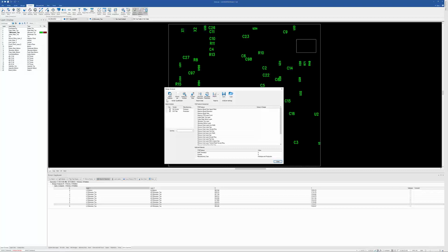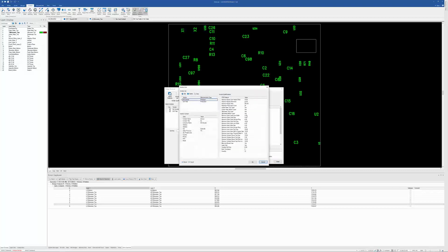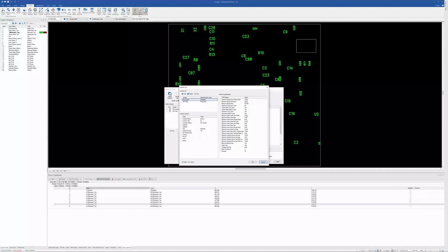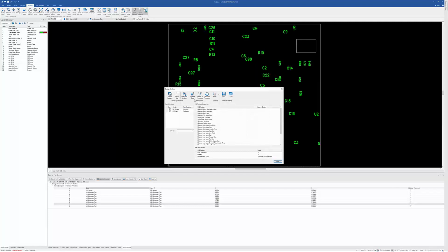the designer wanted more to use this. So what we did is we give you the ability to put in your vendor's capabilities. So if I'm using a couple different board shops, or maybe 20 board shops, I can put their capabilities in here, and it's going to compare those minimums once it extracts them to the board shop and let us know if they can build it. So I just simply hit Analyze the Vendors. It extracts all those minimums and then compares it to my 2 board shops here, and it's going to tell me whether they can build it with a check mark or an X.